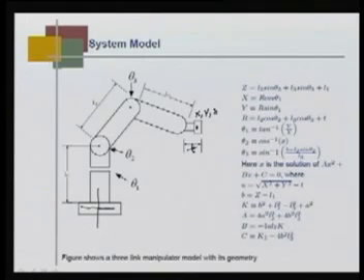Similarly, theta 1 is tan inverse y upon x. So, this is the forward kinematics, that is, given theta 1, theta 2, theta 3, how do I compute the end effector position in the spatial coordinate, in the space, x, y, z. Now, from this equation I derive, given x, y, z, what should be theta 1, theta 2 and theta 3. This is called inverse kinematics.